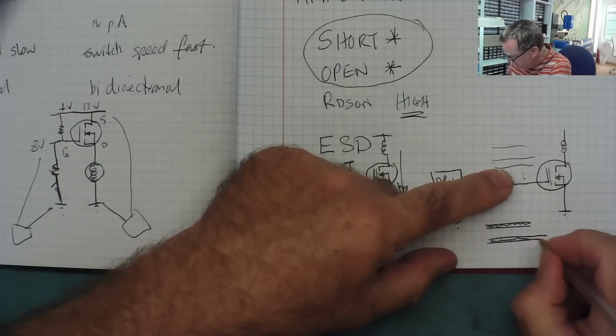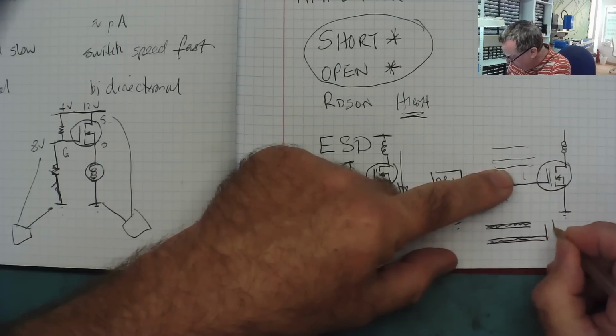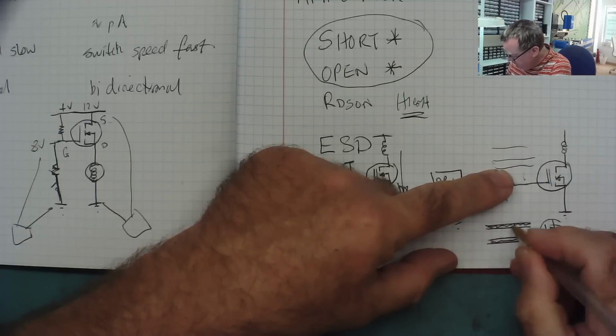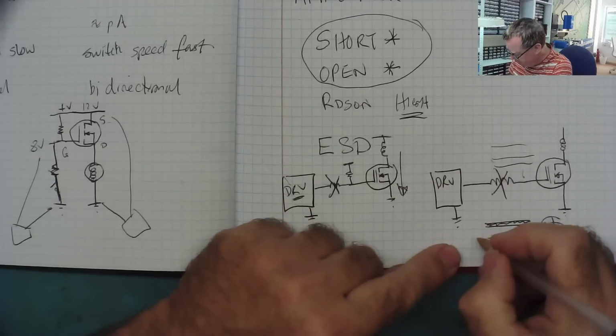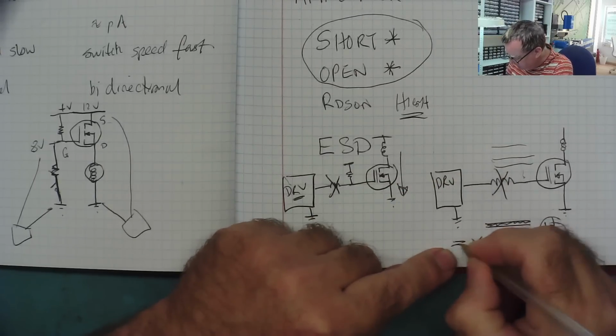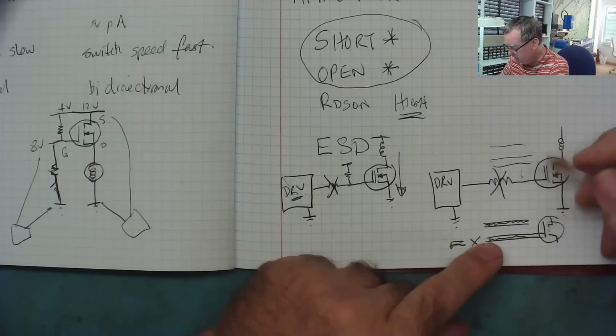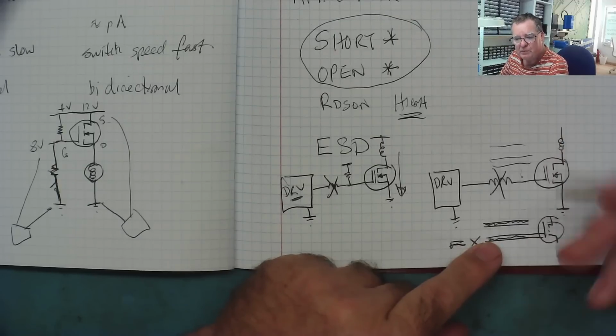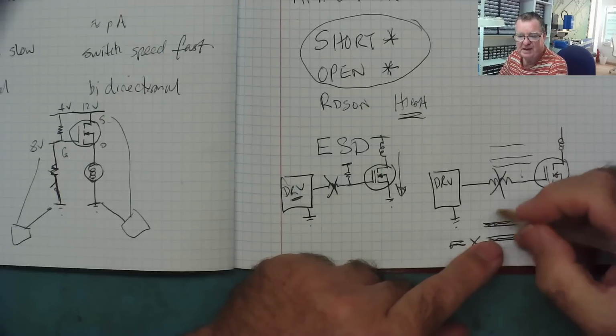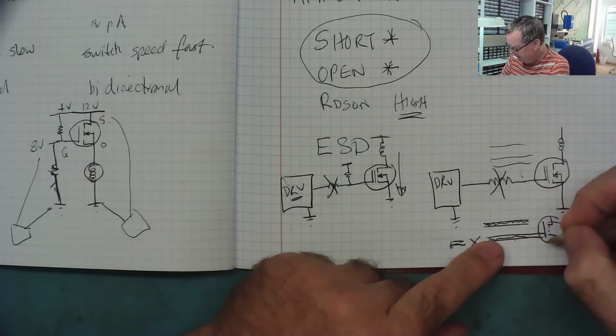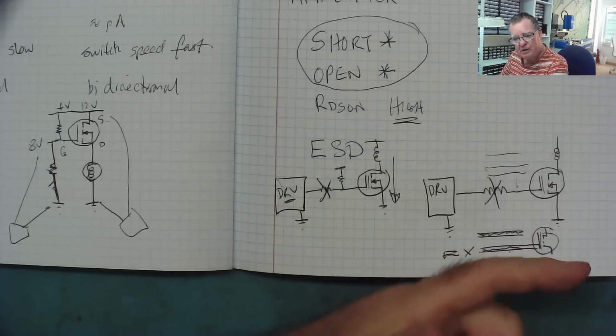And if this conductor is connected to the gate of your MOSFET, and the resistor that's here is open circuit, so there's nothing else connecting to the gate, it's not unlikely that if you switch it on a few times, the surge of current through here will induce some voltage into this, or act like a capacitor. There'll be some voltage on the gate, and this will now turn on.